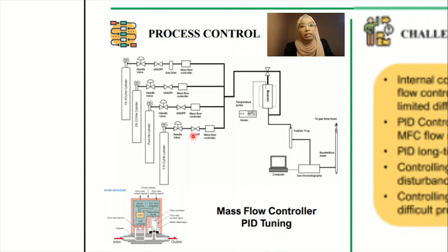The process controller that is used in the system is the mass flow controller. The structure of the mass flow controller can be explained based on the figure below. Firstly, gas will enter from the inlet and split to flow past the sensor or through the bypass. Second, the sensor will detect flow rate as a proportional change in temperature, and it will be changed by the bridge circuit to become an electric signal. The signal will be sent through the amplification and correction circuit, and it will be sent to the comparison control circuit at the same time. At the comparison circuit, the flow rate setting signal will be compared with the actual flow rate and send a difference signal to the valve driving circuit. Lastly, the flow rate control valve makes the difference approach zero.